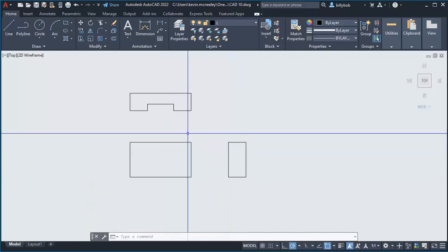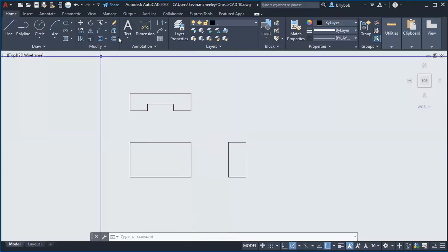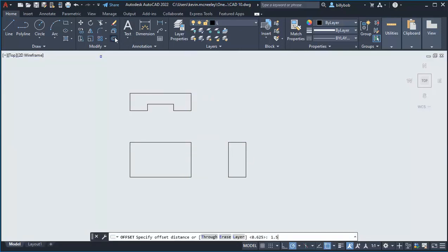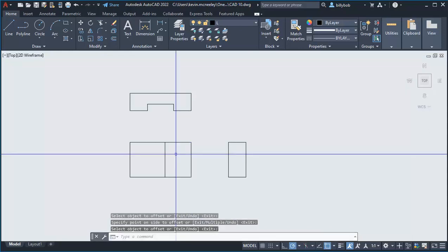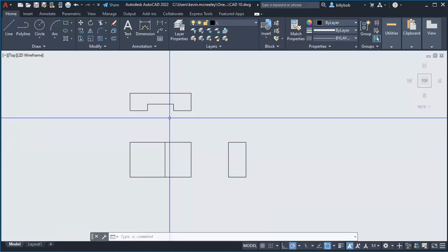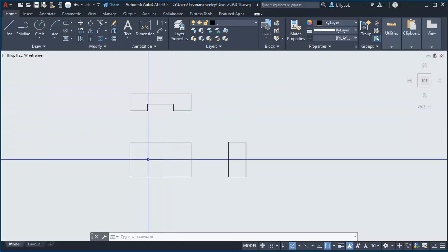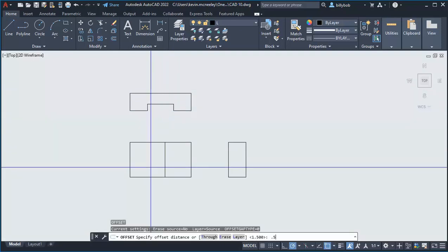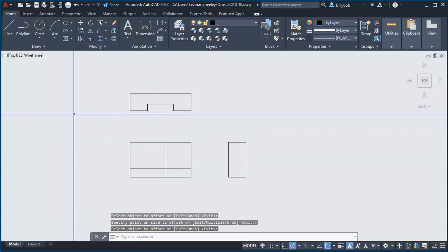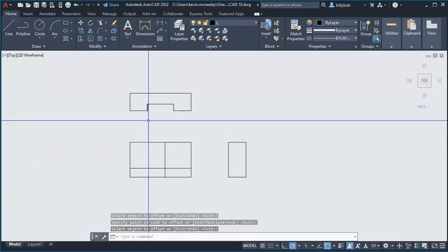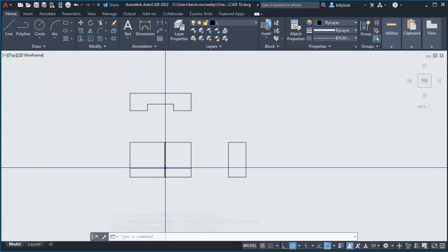Looks like this comes over 1.5 inches, so we do your offset 1.5. Again, offset's going to be your friend, and that's 1 inch. So we're going to offset 0.5. All right, so from there I'm going to draw 45 degrees, right? I find that intersection right there.